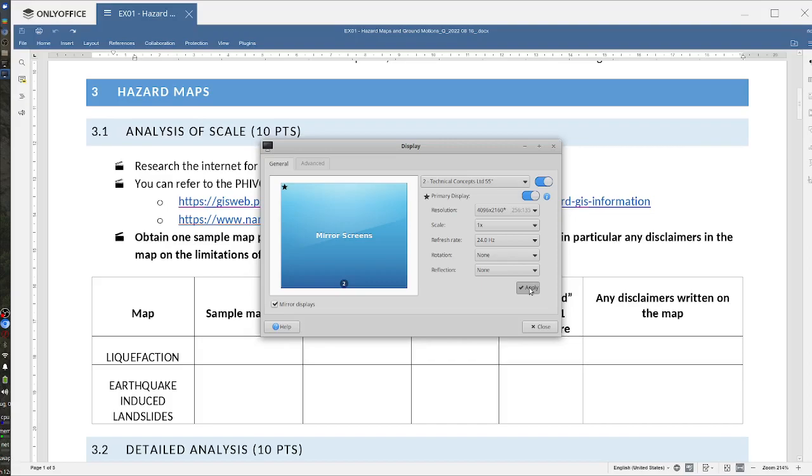So that's what the moment magnitude is trying to address. It tries to address as well the overall, areal size of the fault. And usually the moment magnitude has a bigger range. I think the highest is 9.5, 9.6. Surface magnitude is limited to 8.2. It cannot detect earthquakes bigger than 8.2.